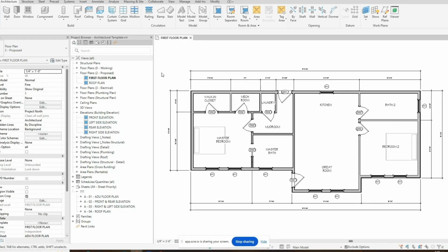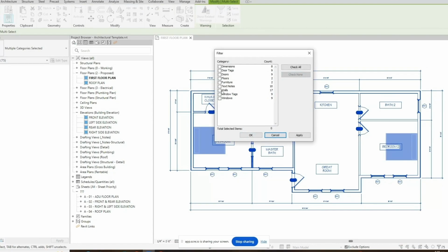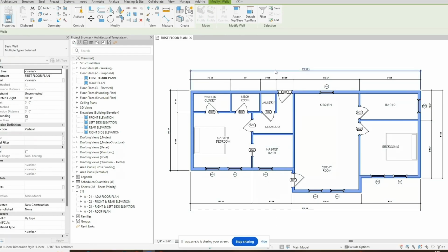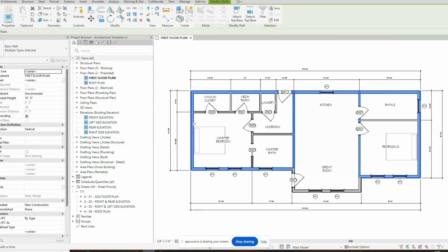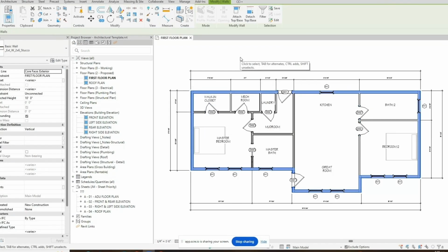Set up your selection filter to isolate only walls, doors, or whatever you're working on. Use right-click, select all instances, then click Visible in View for repeating elements. And when working with connected elements, hover and hit Tab to cycle through selection. Now this tip is perfect for curtain walls or mullions. Once you start selecting things more precisely, you'll notice an instant boost in your speed.